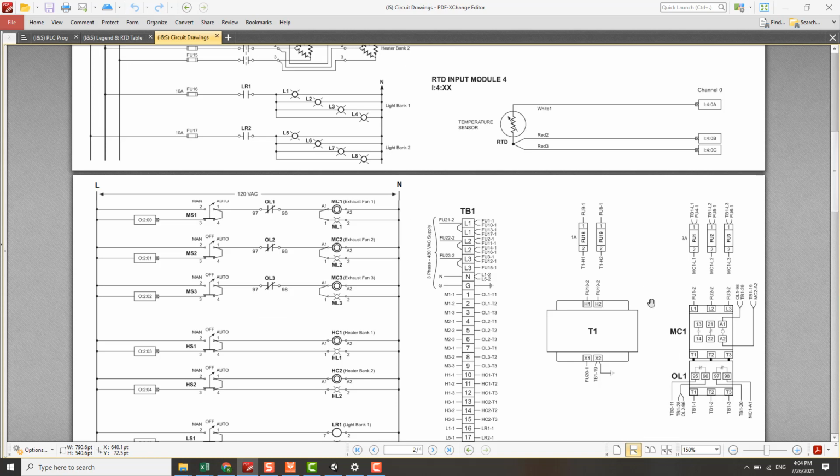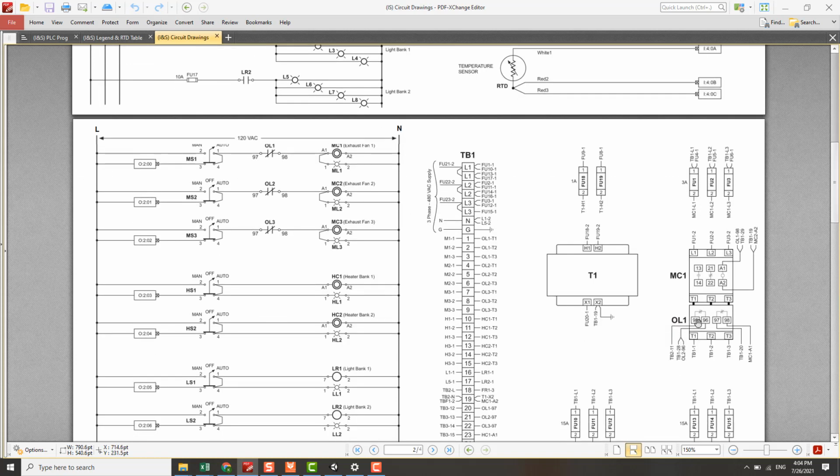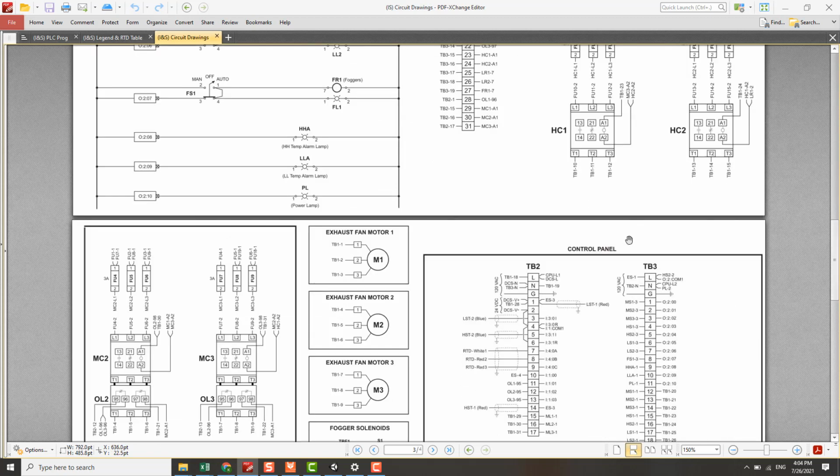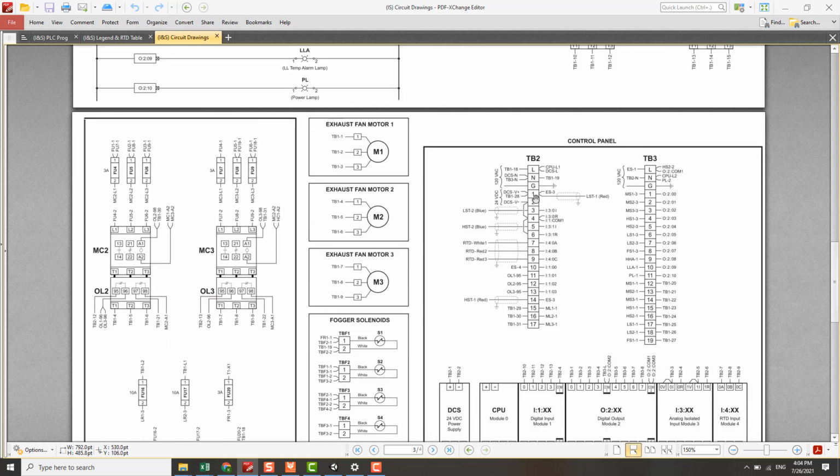Look at the wiring diagram. Overload relay 1, pin 95 is actually from TB2 point 11. TB2 point 11 is here, going to PLC input module 1 channel 1. So we measure the voltage here by putting the red probe of the multimeter at point 11 on TB2. What happens is the DC current will come through here and divide into two paths, one path to the load, the other path to the multimeter.